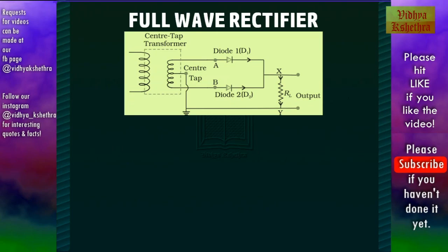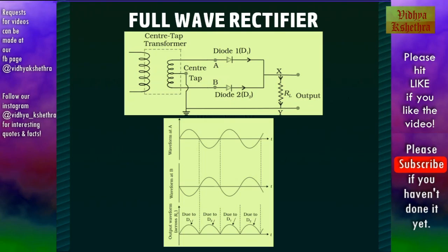In this case, the input voltages at A and B differ by a phase difference of 180 degrees. That is, the waveform of A is shown as well as the waveform at B. Now, when A is positive, the voltage at B is negative, and hence the output voltage we get through RL, the load resistor, is through D1.